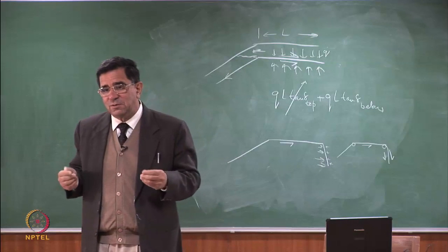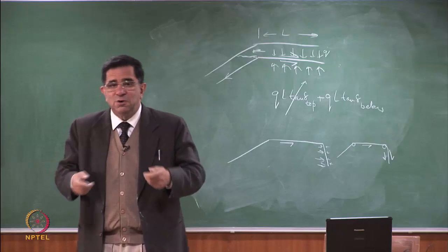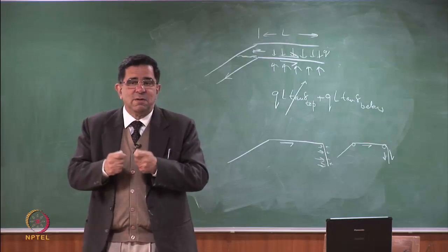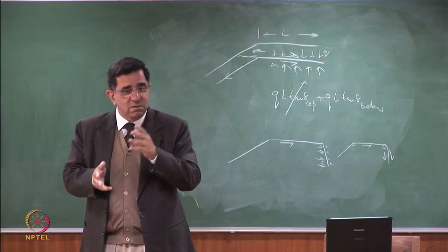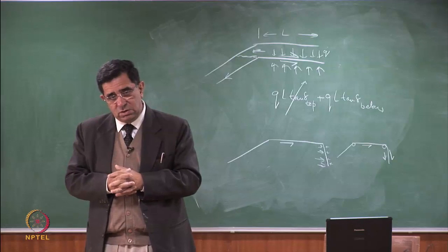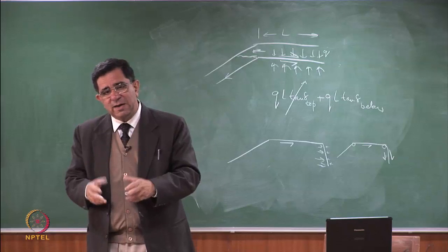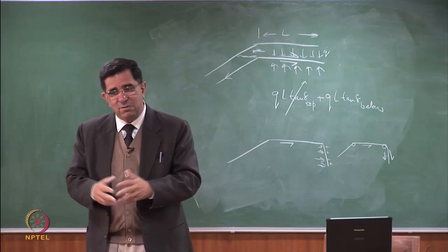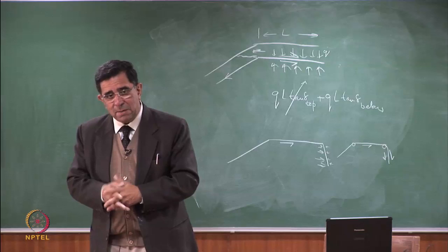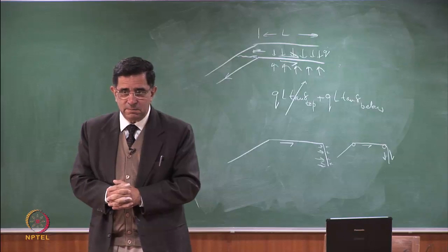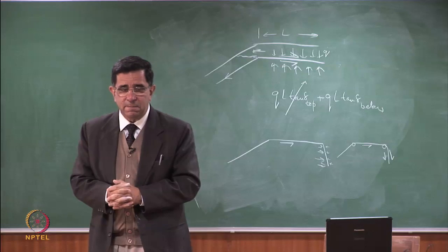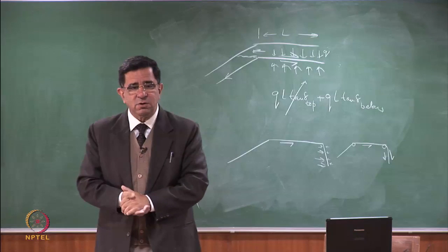You can use berm heights of 7 or 6 meters, but you will need to hold these in position, and design of anchor trenches is a current area of research. Anchor weights, anchors, run out lengths, wrap it around a pipe, all kinds of work going on in this area. So thank you, and we will continue in the next class.